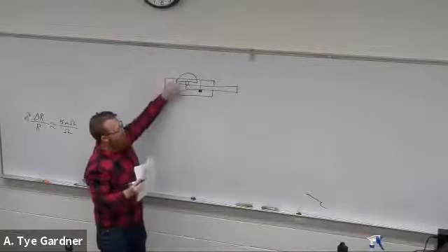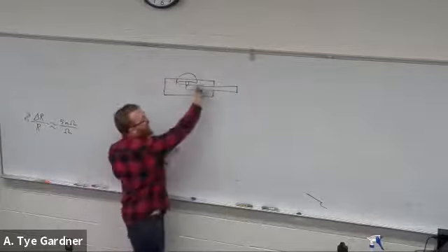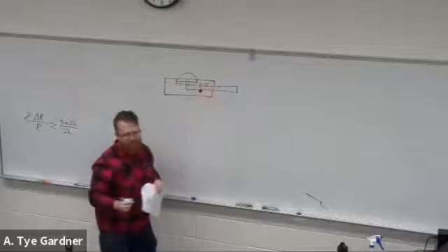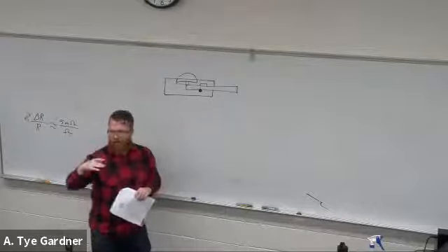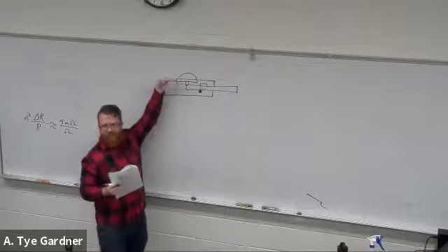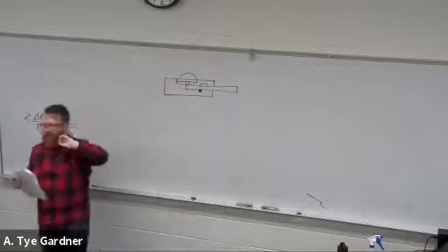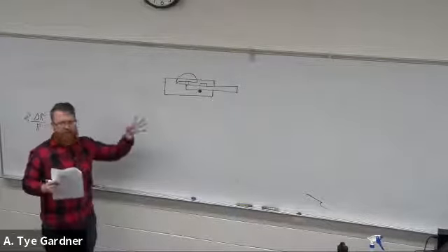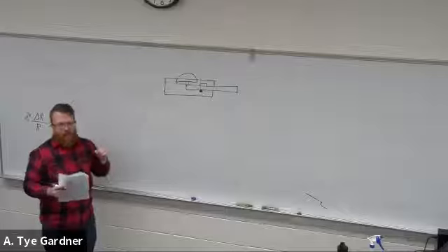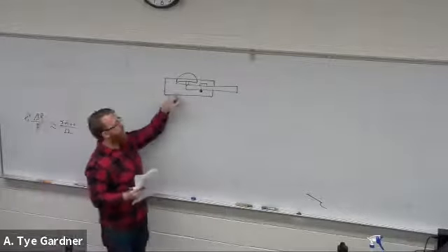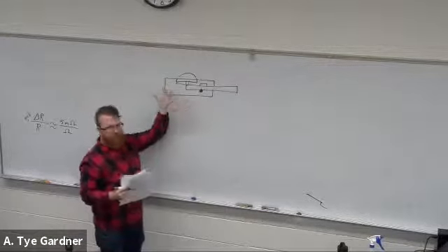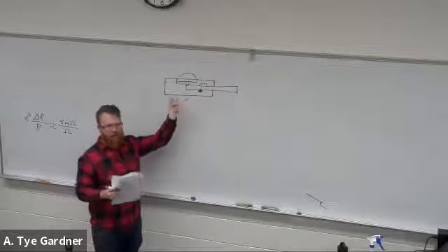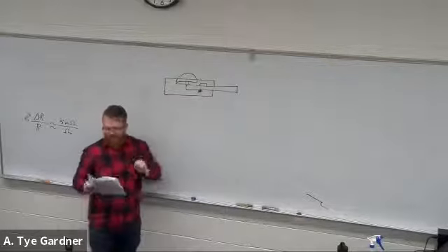And as you push down, it gets deflection, and then your strain gauge would be like here. And it would measure that deflection as you push that button. So that's one way that you would use a strain gauge as a force sensor, right? And as long as you know the acceleration, which is gravity, then you can measure the mass.